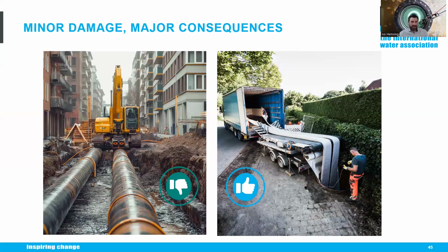I just want to point out that these common types of damages or leaks in water systems can be rehabilitated using UV CIPP technology, resulting in a new estimated service life of at least 50 years. And also the host pipe material doesn't matter, if it's PE material, asbestos, cement, steel, iron, it doesn't matter. As shown in the picture, liners do not require large chambers or excavation pits, and are very well suited for urban areas like cities, helping to protect the environment, trees.